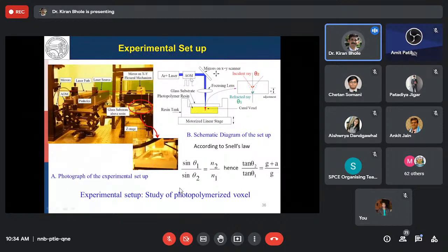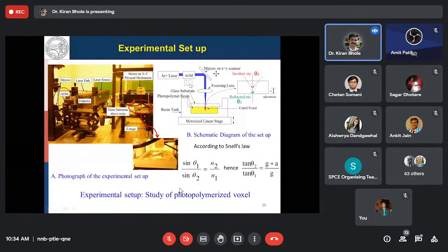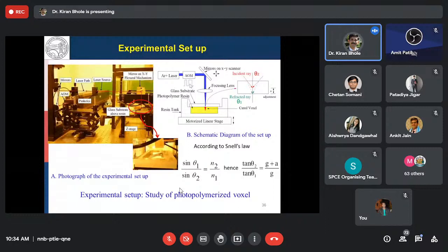And this is the acoustic optical modulator, which is playing a very vital role. As I said, it is not performing only the function of on and off as in the case of MSL, but it is performing the function of varying the energy exposure while scanning. Because while scanning, we have to vary the energy exposure to fabricate the device. So this is the added function for the acoustic optical modulator to perform in the bulk lithography process.